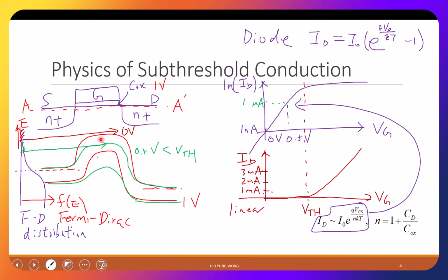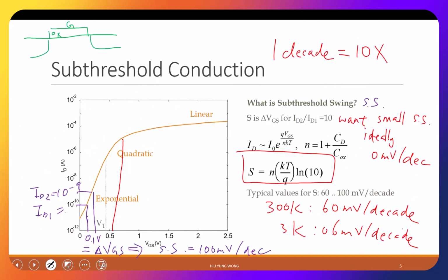We do not touch it directly. We do this through capacitive coupling. What is really happening is this. We go through this capacitor to the surface of the transistor. And then remember, we have a depletion layer, and this depletion layer is connected to the ground. So actually there are two capacitors, and what we're trying to change is this voltage, which I will call Vx. So what is Vx?